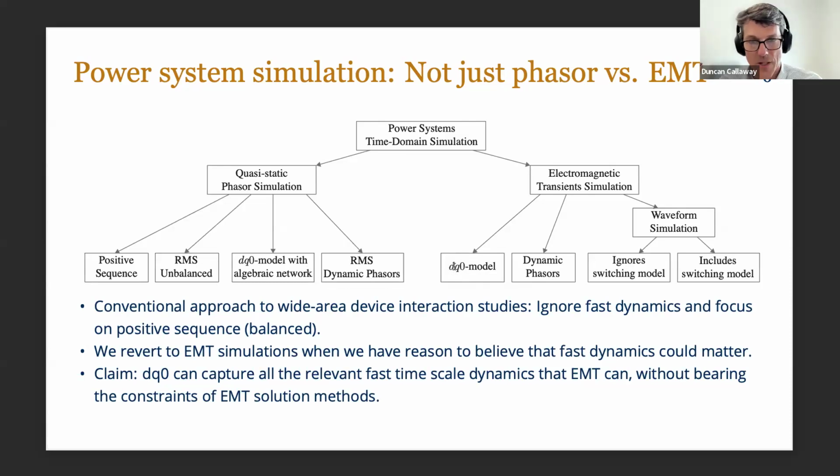So if you study DQ transformations, DQ, very importantly, is not an approximation. It's just a mathematical transformation from an ABC coordinate frame. So you're taking a point-on-wave mathematical representation and representing it in this DQ formulation without any approximations. It's just a mathematical transformation.